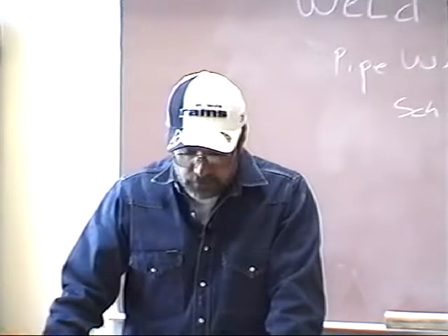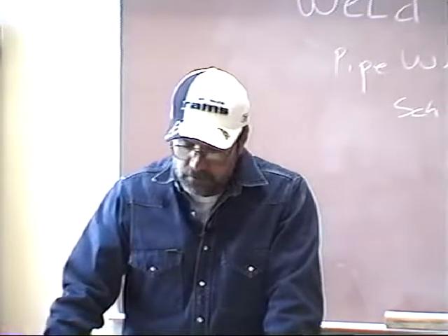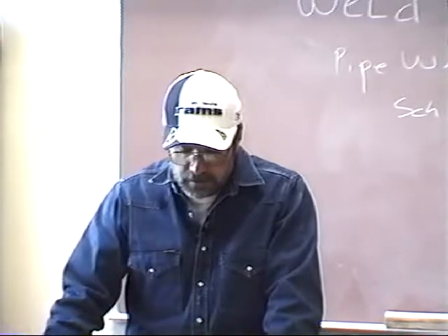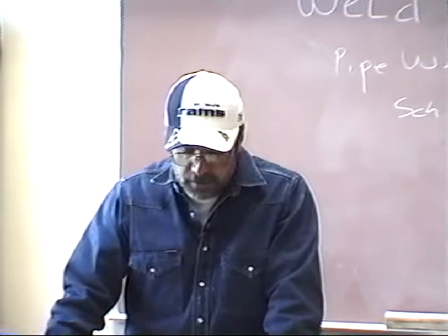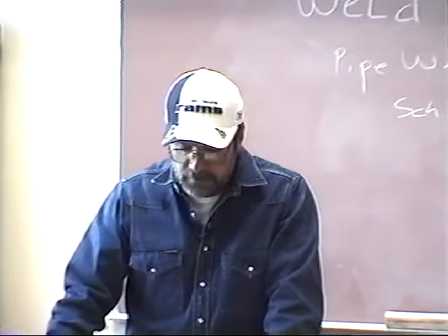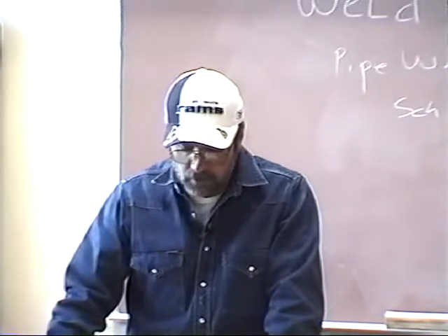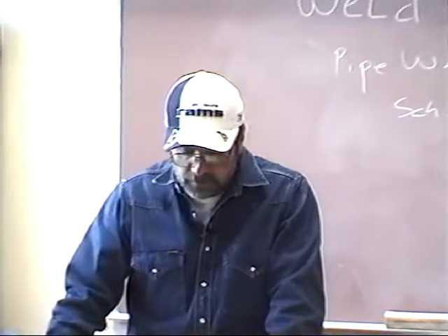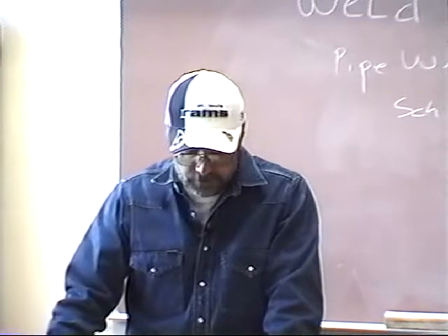When the puddle of molten metal is moved back and forth in a uniform manner across the weld joint, the heat in the area close to the weld is spread out. This technique is called weaving. It is used to spread the heat and to obtain a wider weld bead without maintaining an excessively large puddle of molten metal. Whipping and weaving will be treated in greater detail in later chapters.